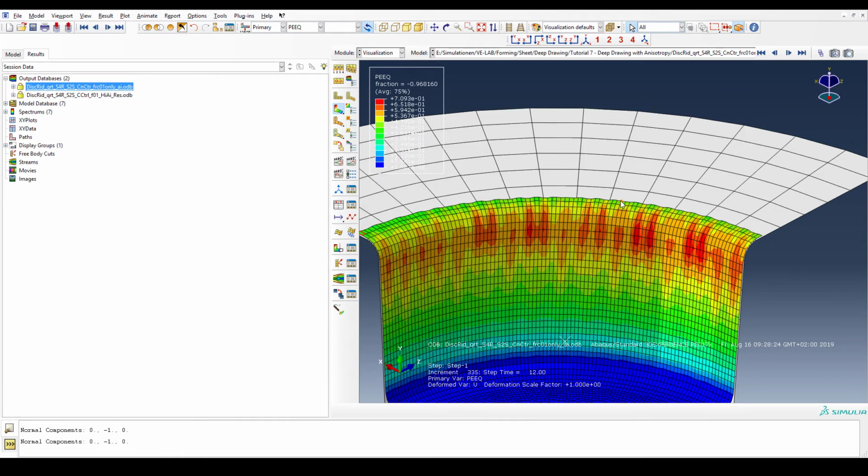So where does it come from? We talked about this in the previous video, that you have different definitions of your blank holder. If you keep a certain gap between your sheet, and I'm talking, since we did not exclude the shell thickness, about the actual model thickness, which was 0.8, and whatever fixed gap there was between the blank holder and the die, it gives room for the sheet to show this wrinkling behavior, right? This first order wrinkling, because this is what the sheet wants to do. We talked about this, right?